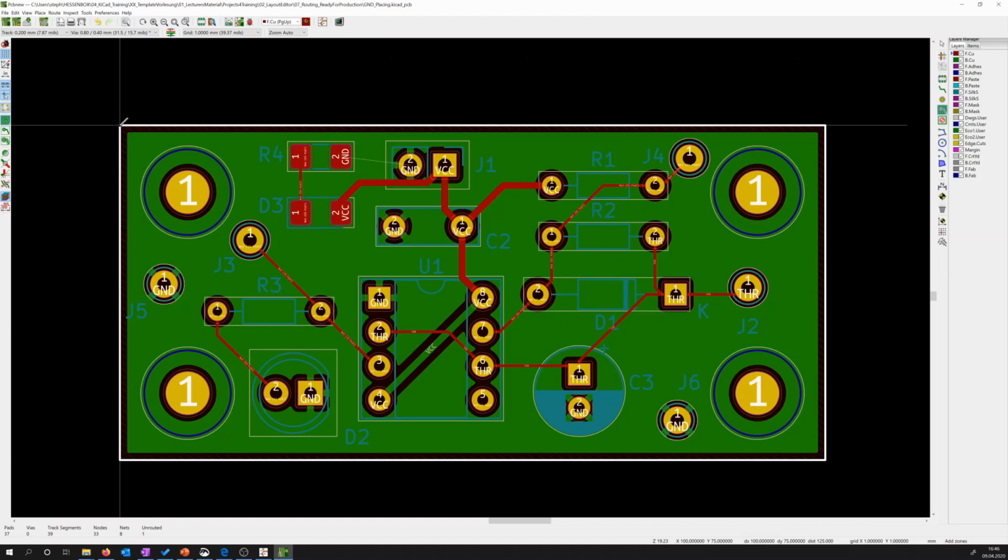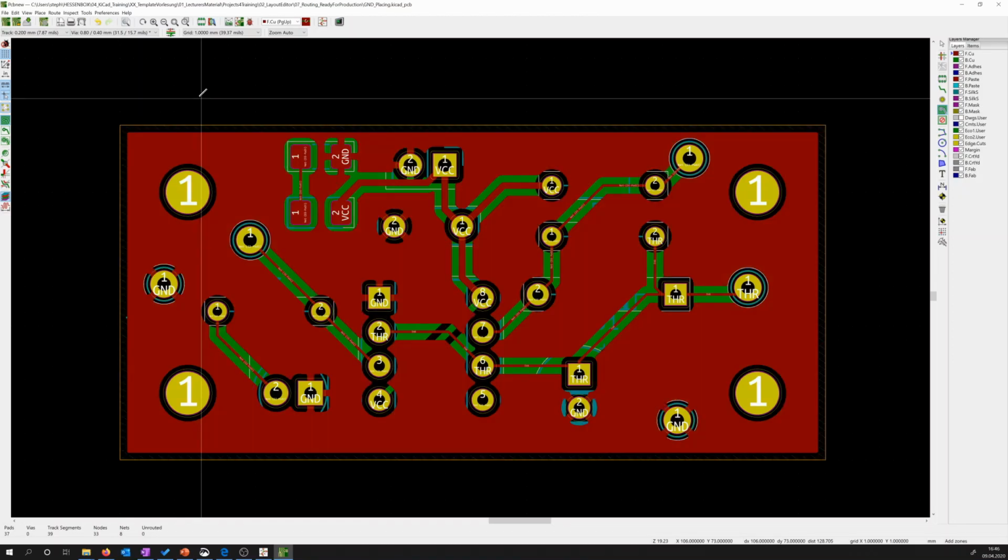Once this is done, we deselect our filling tool with escape. And now you see that all the ground pad of our resistor or diode, I don't know what it is, is also connected with these 4 pieces or legs. This is maybe interesting to see because you can say, okay, the whole front plane is ground. Why do I have these spacings?